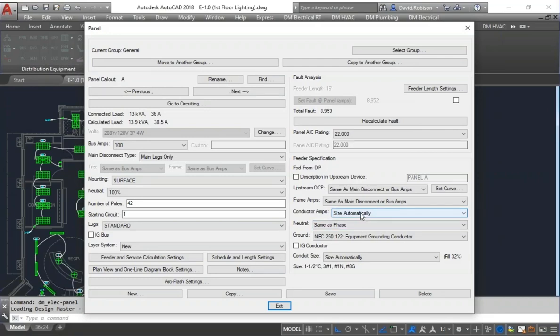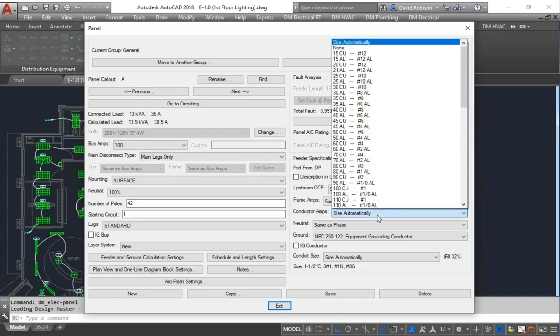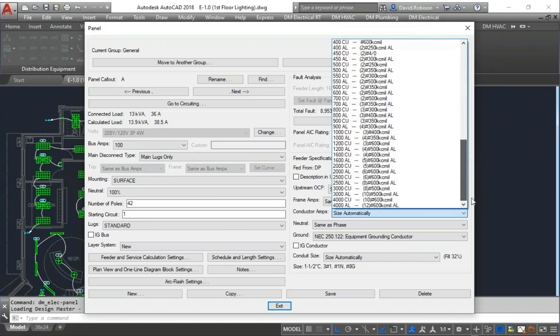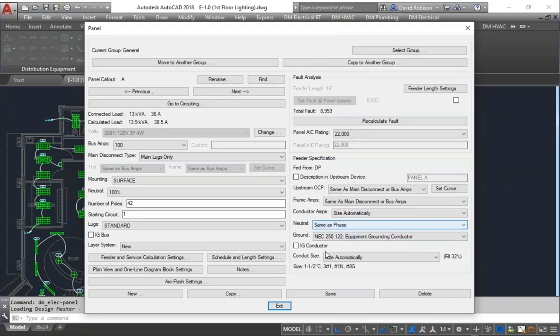So we're going to size the conductors based upon the overcurrent protection, the breakers, based on the size of the panel. So basically we get a 100 amp wire. But you can choose a different size. And if you go down here to our larger sizes, you'll see that they actually stop at 600 kcmil. We don't have anything bigger than that listed here. And the customer specifically wanted a 750 wire.